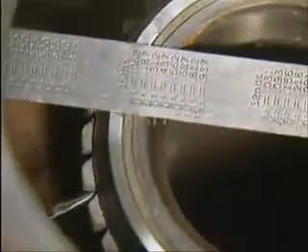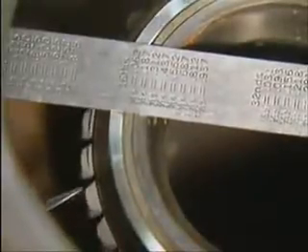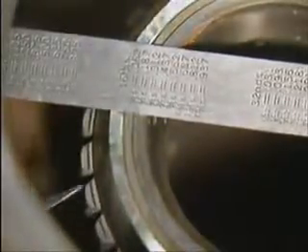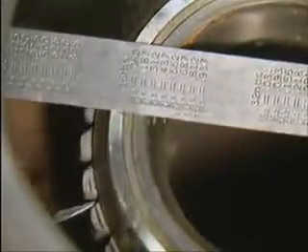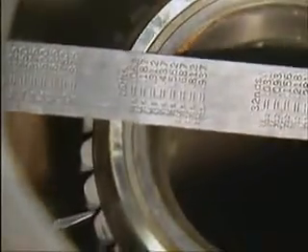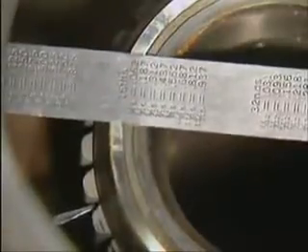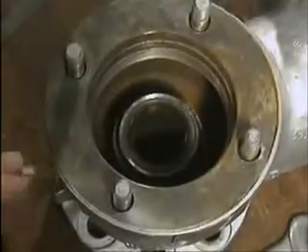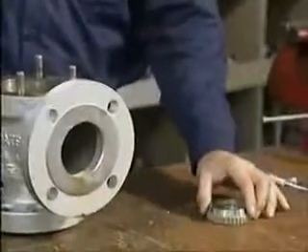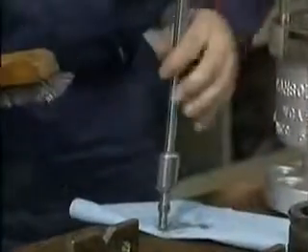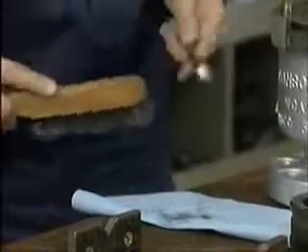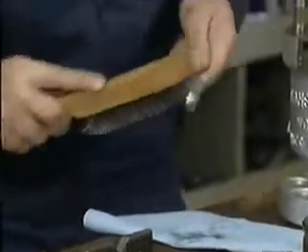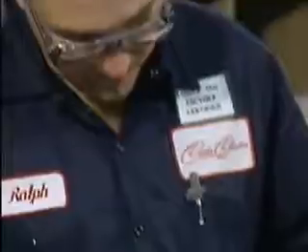Count each notch as it moves past the pinhole while the ring turns. Write down the total number of notches that you counted. This number will be used to install the ring correctly when the valve is reassembled. Remove the rule and unscrew the lower ring until it disengages from the threads on the valve body. Then set the ring aside. Finally, follow your facility's procedures or the valve manufacturer's recommendations to clean all the disassembled parts.